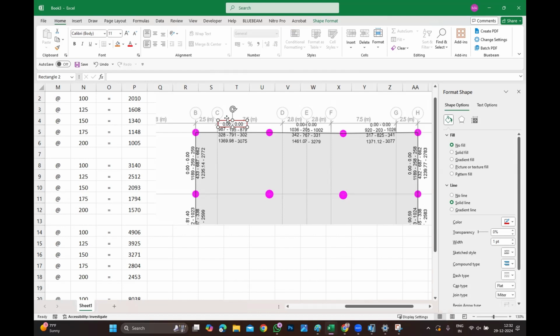The first number 0, 0. Imagine there is like 100, 200. The first number is left support shear here. The second number is right support shear. I'm only talking about this beam. Yeah, 1/3 actually. The second number, all three numbers, are for top rebar. In the second line, the first number represents top left, top middle, top right.